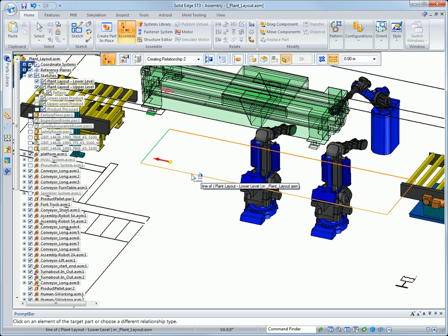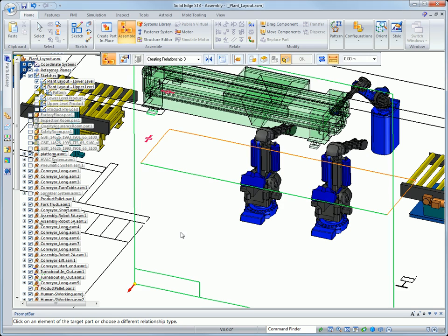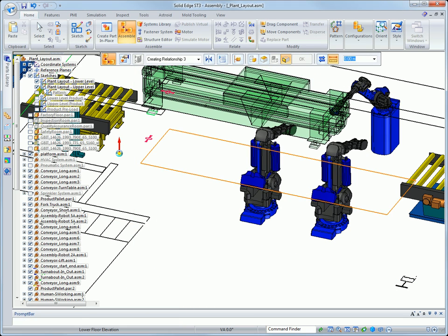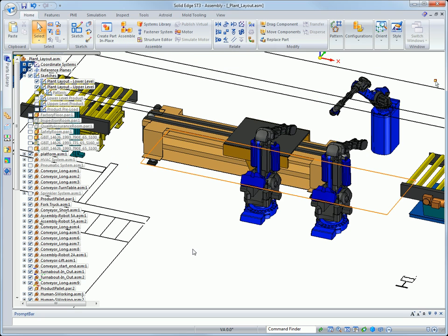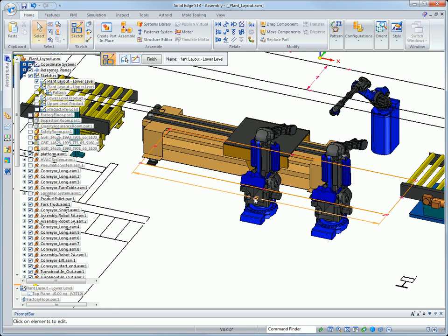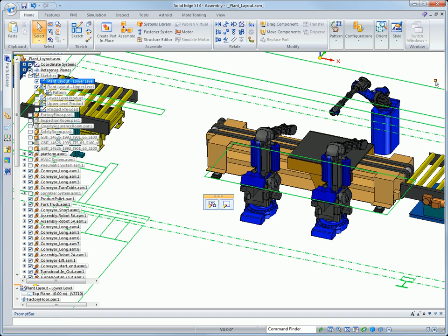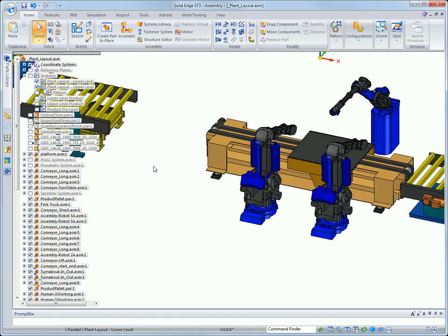Typically, we would think to add components directly to the others, but in the early phases of plant layouts, these parts may not be ready. Solid Edge allows us to easily place 3D components directly to the 2D sketch. Since the layout defined the spatial location, why not have that same layout drive any changes? We call this a hybrid approach to the assembly design. A quick dimensional change of the layout sketch shows the 2D elements can set the position of the newly added vendor assembly.